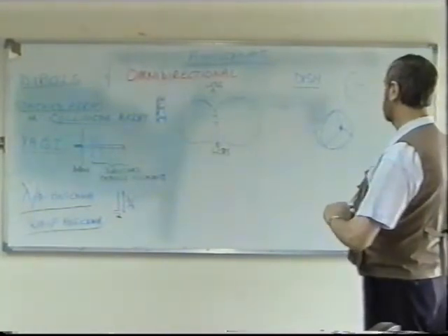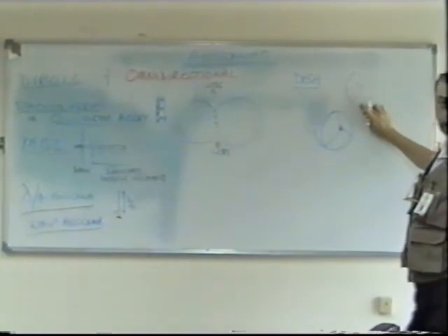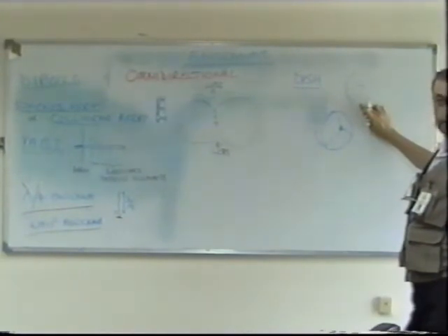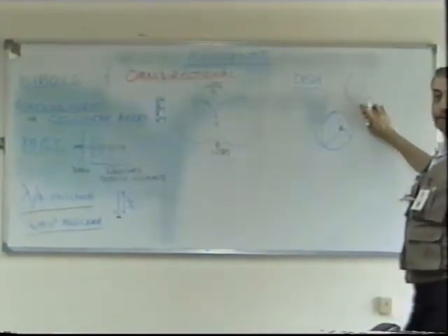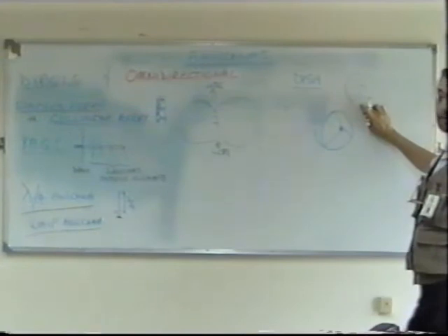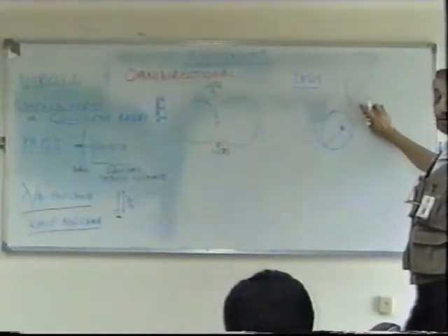Some types of microwave, don't forget a dish can be used at any frequency. If I wanted to use a dish at, say, medium frequencies, yes, but it's going to be a very, very big dish. Remember, the dish has got to be many wavelengths bigger than the wavelength of the frequency you're using. Medium frequencies are, say, 300 kilohertz to 3 megahertz. Work out the wavelength of that, and you've got several hundreds of meters.